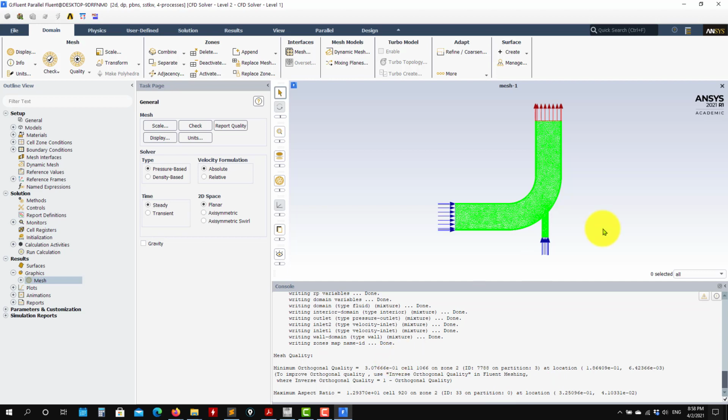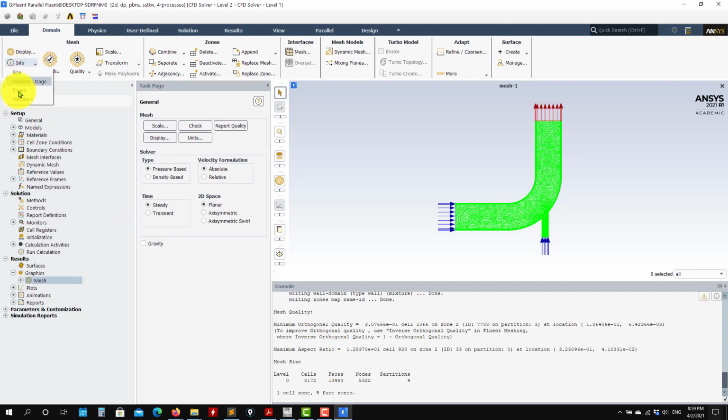You have it. Usually with 2D you're always going to get good quality meshes. In 3D is where you start to have problems. But I mentioned that this is an important value. Let's say for good meshes, this value should be more than 0.01. Less than that means that you have a mesh quality problem. It doesn't mean that you cannot run, but maybe you may have some artifacts in your solution, something that will affect your solution. Might be, might not be the case, okay? But usually 2D meshes are okay. Also in 3D, the Ansys mesher works really well. So you go here, you also have the number of cells and some general information. So here in this tab, you have all that stuff.